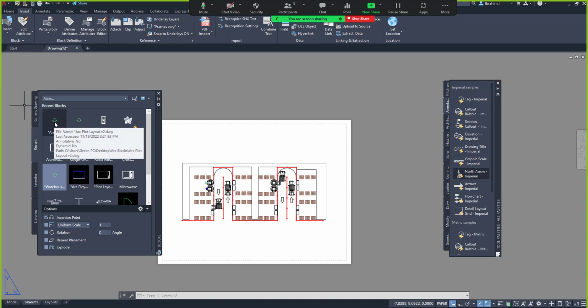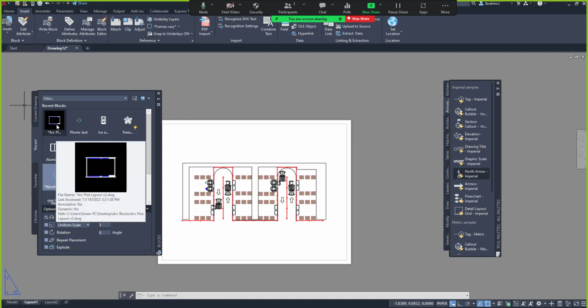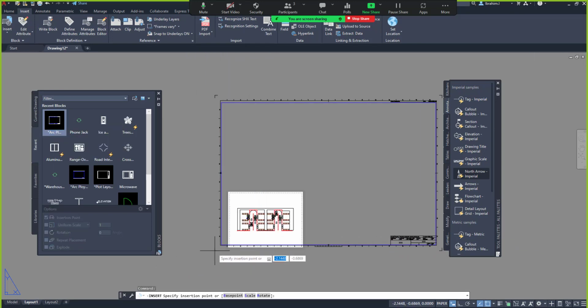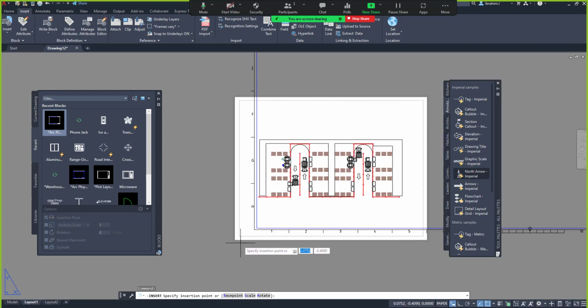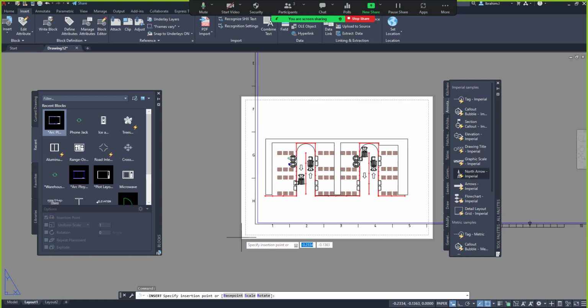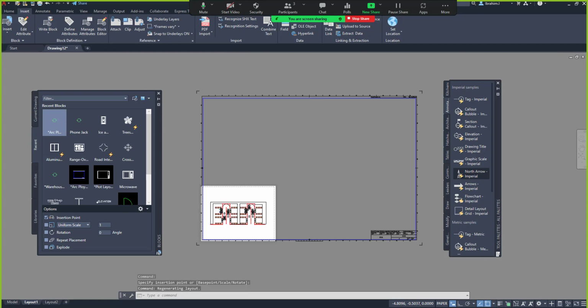But the new one that I just created is still synchronizing. That's why I'm seeing that arrow that is rolling around. Can you see that? But now it's showing, right? When I click on this and click on Insert, what happens to my design? It's asking me to specify the insertion point. Most of the time, you want to have a rectangle that has been created already, so that I can place it here. You can place it at that end point. But I'll just use my visuals at this stage to place this object here.